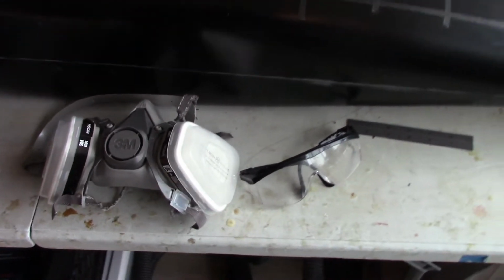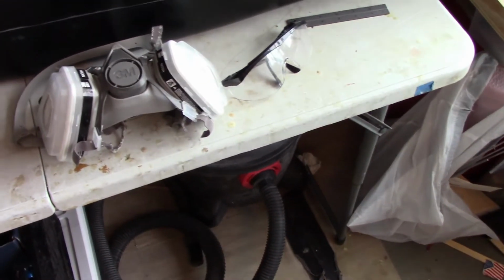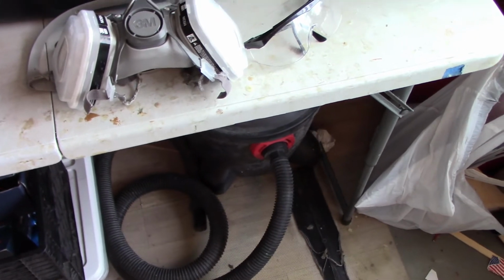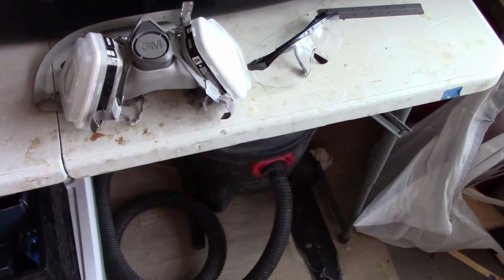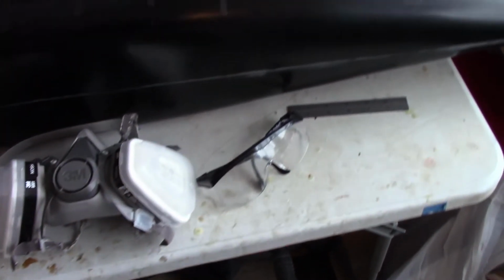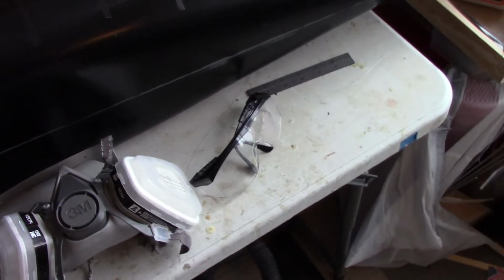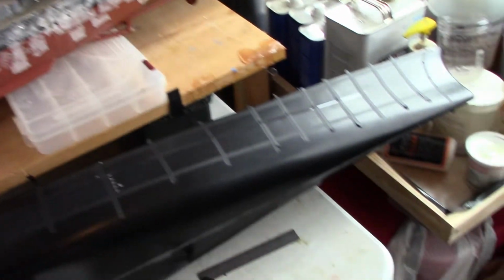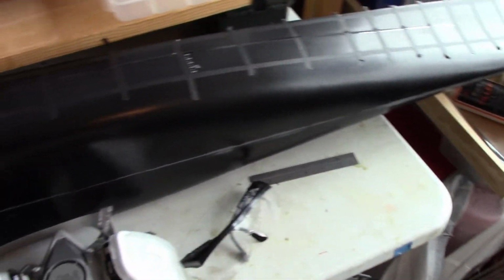When I do this work, I'm in an apartment. It's in a sealed off area, but it's still directly adjacent to my living area, so I'll use a shop vac to suck up the dust immediately at the point of creation. So I usually have one hand on whatever the tool is, whether it's a drill or the Dremel, the other hand with the shop vac, sucking up the dust. You'll still get some dust, so if you have other boats in the area, get the decks on, because the dust will settle everywhere.